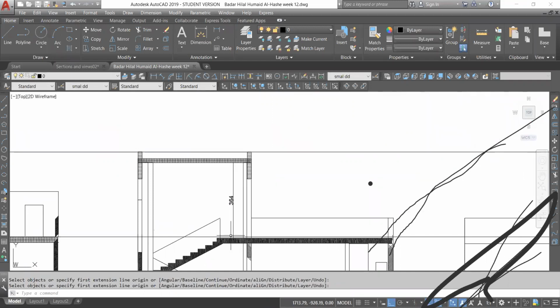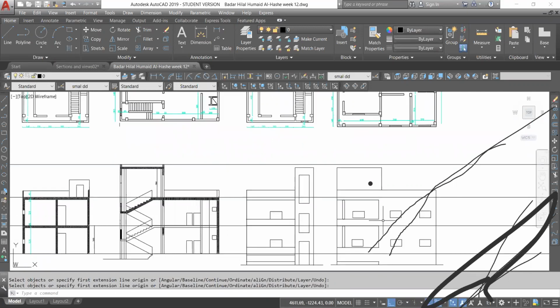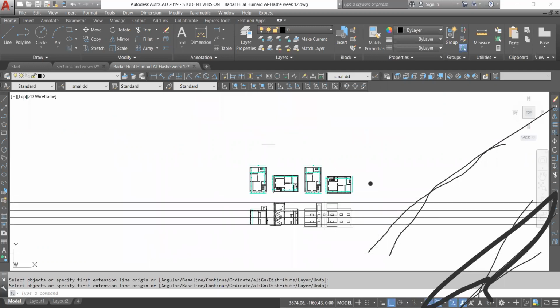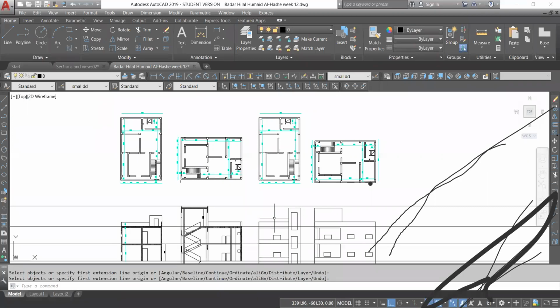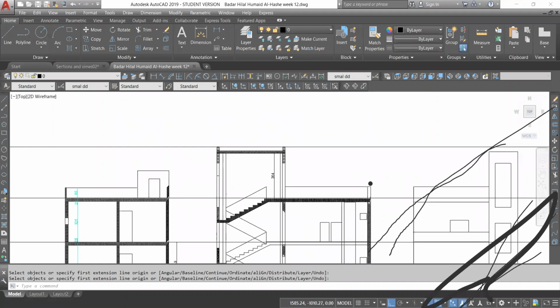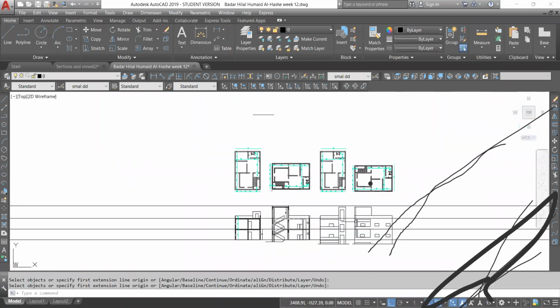The height must be 220, not 364. So the alignment is not correct. So please redo this drawing again, use object snap, correct the connection between lines, and keep the alignment between sections and view. This is another example.